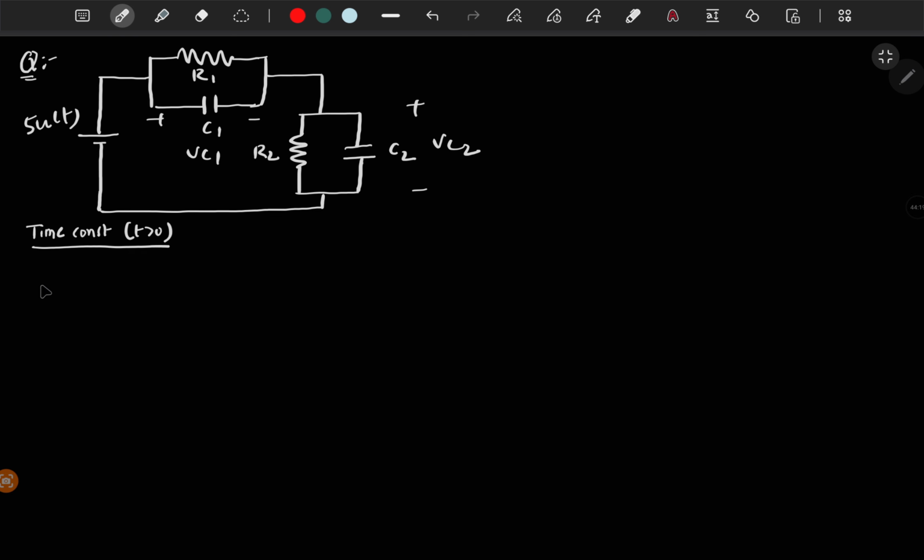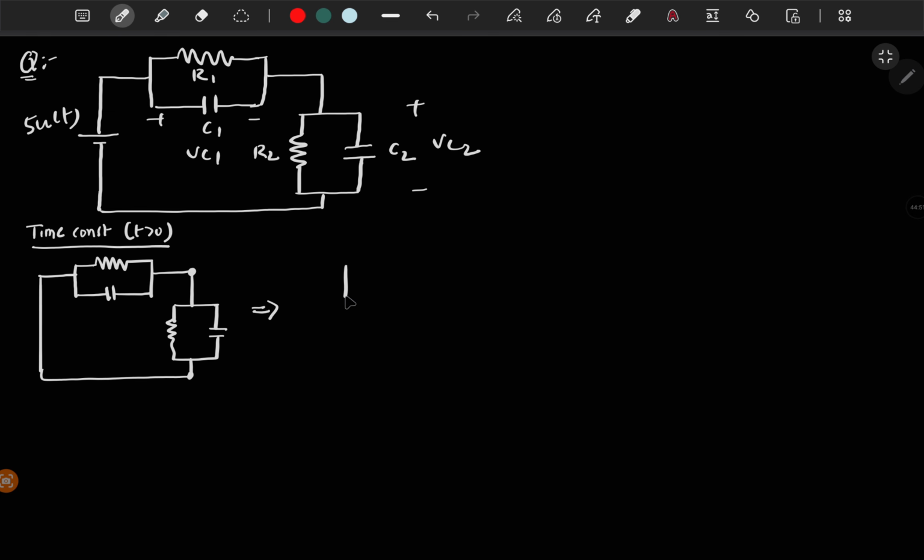I'm sorry. So the voltage should be short circuited and you have a resistor and a capacitor, and a resistor, capacitor. So between these two terminals all the components are connected, these two resistors and two capacitors. So this you can represent as a resistor of R1 R2 by R1 plus R2 because these two are in parallel. Then a single capacitor of C1 plus C2.